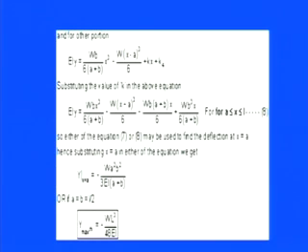And if the load is not acting exactly at the middle but somewhere else in the beam, at a distance A from the left-hand side as we discussed in the previous case, then the maximum deflection at that point is equal to minus W A square B square divided by 3 times EI into (A plus B). So that is how these variations could be worked out.